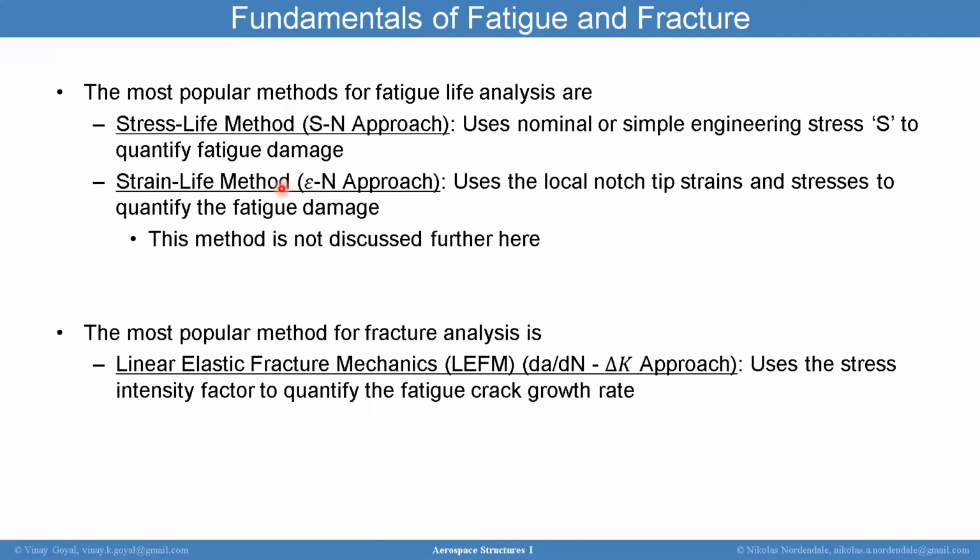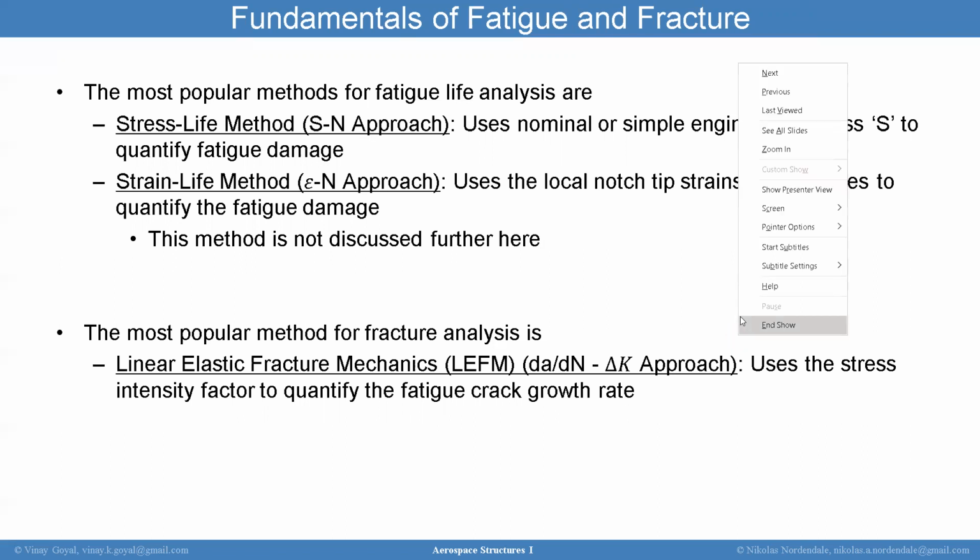These two approaches are covered in the second portion of this course, but the bottom line is if you have repetitive loading at a particular stress, the number of cycles to failure could be finite. And typically you'll use the S-N approach for high cycle fatigue and the strain life approach for low cycle fatigue, meaning high strains, typically beyond yield. The most popular method for fracture analysis is linear elastic fracture mechanics, using the da/dN versus delta K approach, also covered in the second portion of this course. It uses the stress intensity factor to quantify the fatigue crack growth rate.